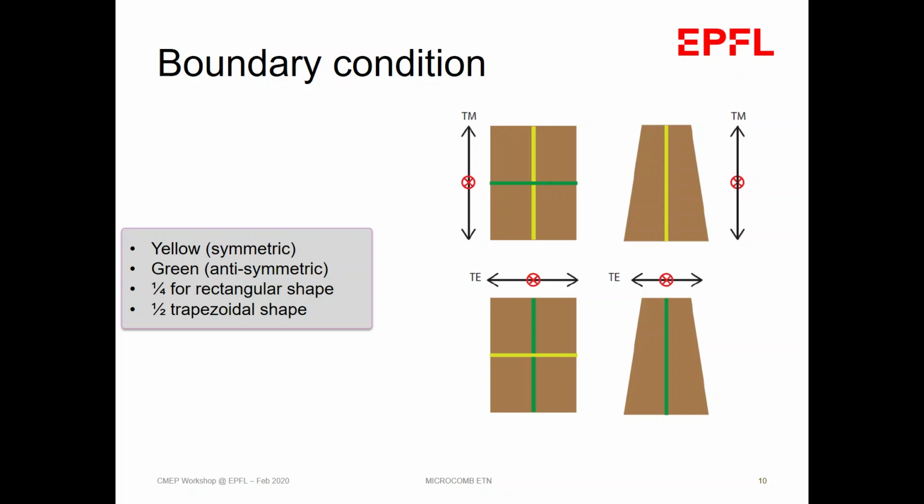What is the accuracy difference that you get there? Because when the mode transitions are all very adiabatic, it shouldn't make a difference. I think it will, but it depends on the length of your taper. Yeah, exactly, if it's very adiabatic, it shouldn't. Sure, when you go beyond 100 micron, then I don't think so.